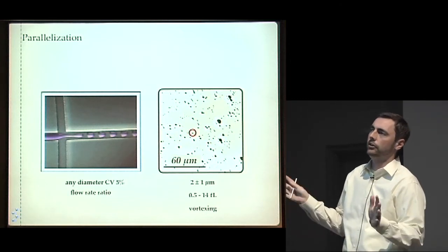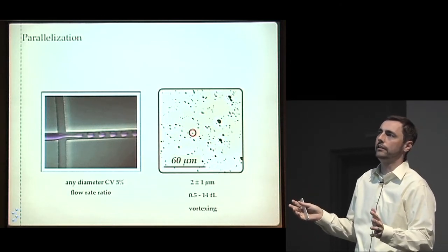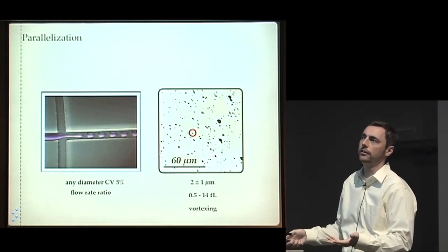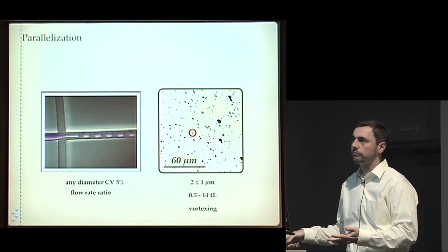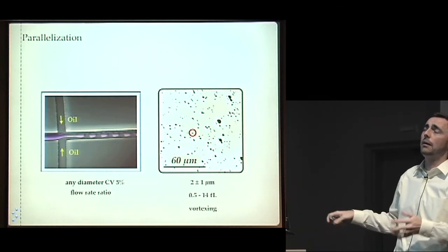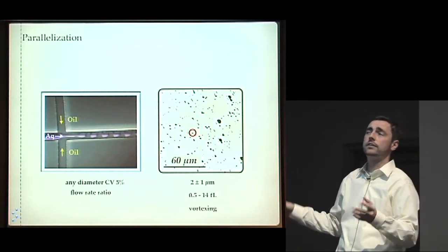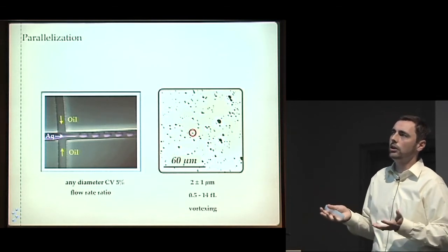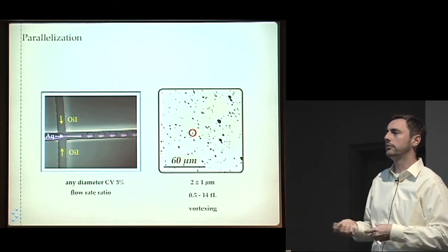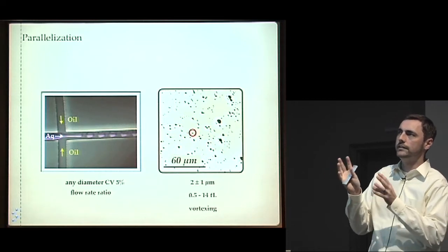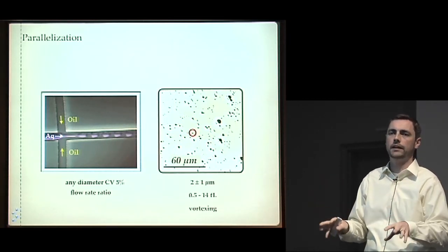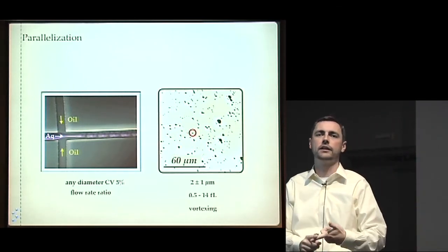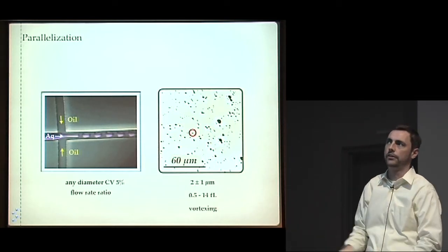So it turns out there's an elegant solution in microfluidics for making stable water droplets in oil, and it's a very simple circuit design. It's shown here on the left-hand side, where oil phase is coming in from the top and the bottom channels, and our aqueous phase is coming in from the left-hand side, and these are literally pumped in by syringe pumps. And now we're no longer cooking. We're not mixing some oil and some stabilizer and putting the blender in. We're actually doing science. We have syringe pumps at known rates that are pumping fluids in. We have a circuit geometry, which is in my AutoCAD file, and I can ship it to any lab in the world, and they can put this system together and make droplets.